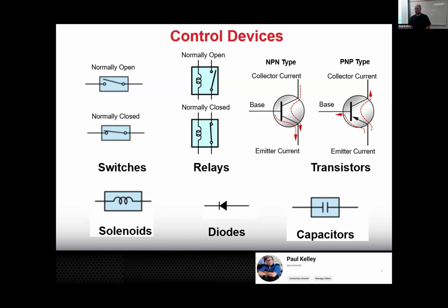So you remember we started with strategy-based diagnosis, right? Remember how we were trying to say you don't want to be like, oh, your car doesn't start, the fuel pump's not pumping, let's start with the fuel pump. You want to see, is the fuel pump getting the voltage?